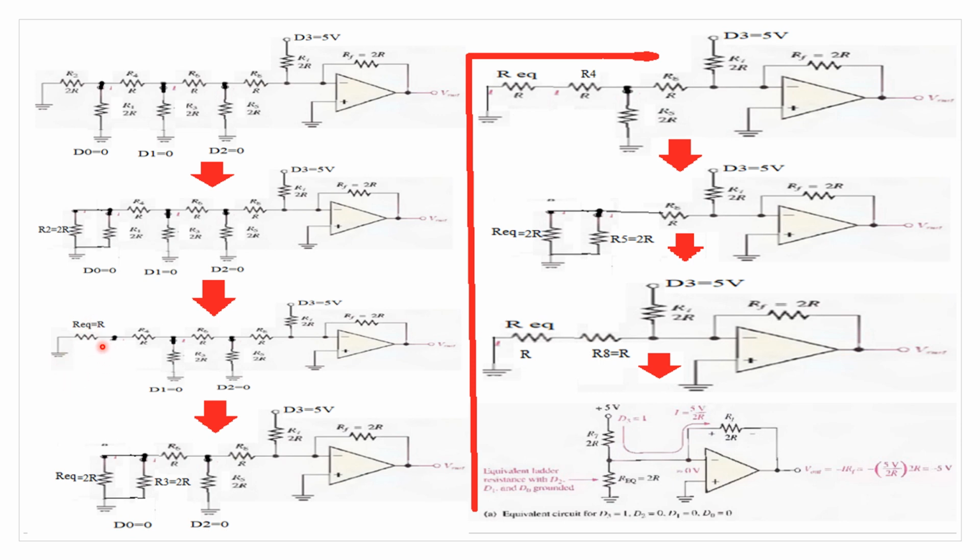Now we can see that these two resistors are in series. This of value R and this of value R, both are in series. Hence the equivalent resistance will be R plus R, that is equal to 2R. We can see that this 2R will be parallel to this 2R. Hence the new circuit can be drawn like this.